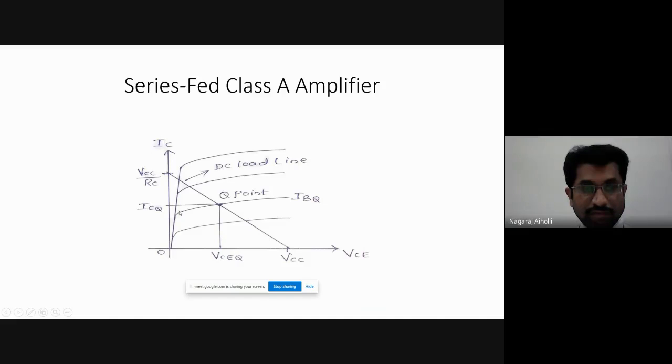For the graph of the collector current versus the collector to emitter voltage for different fixed values of base current, that is nothing but the output characteristics, also called the collector characteristics. Now for different values of the base current, suppose this is IB equal to 5 microampere, then as I increase VCE, IC is increasing, and when I further increase VCE, IC remains almost constant.